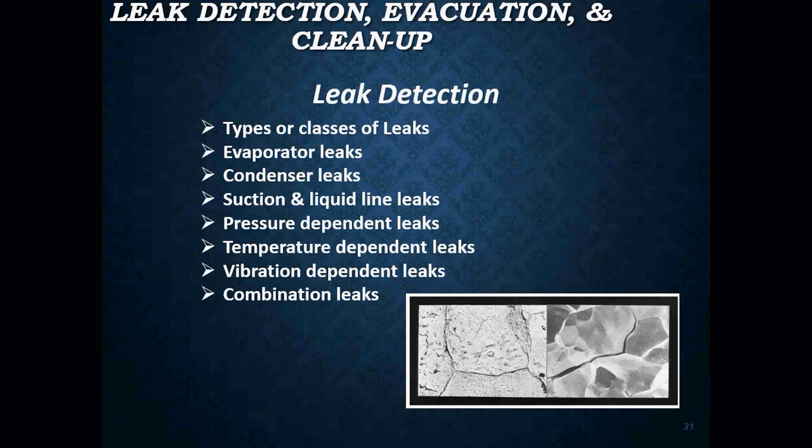It's like, oh, okay, it's a leak. Oh, it's probably going to be in the evaporator or condenser, right? No. There are times where you're going to have issues with a system that has a leak, but that leak may not necessarily show its ugly face until the refrigerant lines reach a certain temperature, or if those refrigerant lines have been vibrating enough to start showing its ugly face.